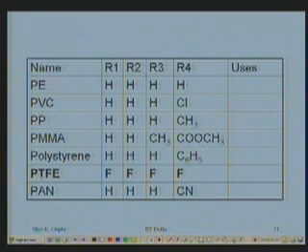Civil engineers exploit this in push launching of bridges. The girder they make is, let us say, the span offshore, and the piers are already made in the stream. Over the piers, instead of lifting it with a crane and putting it over the piers, it can simply be slid with the help of jacks, screw jacks, or hydraulic jacks. The capacity of the hydraulic jack has to be just 1%. If the coefficient of friction is 1%, it has to be only 1%, not the dead weight.